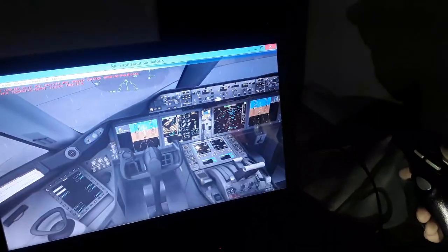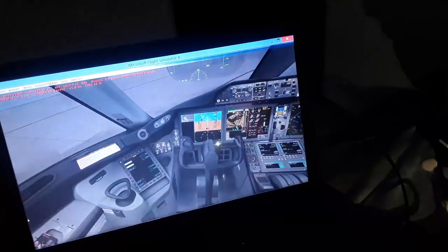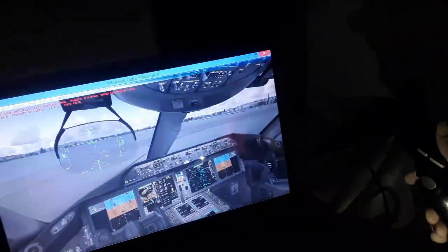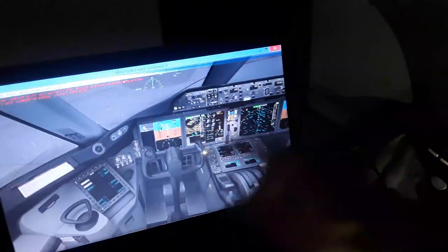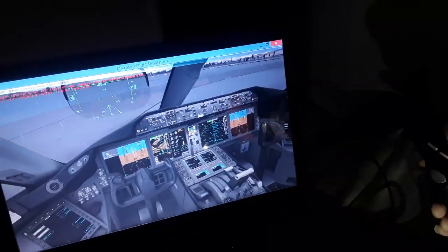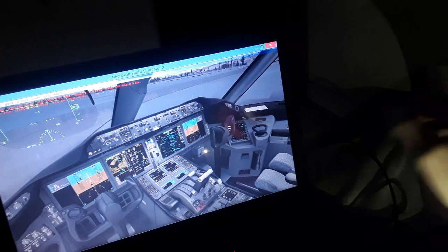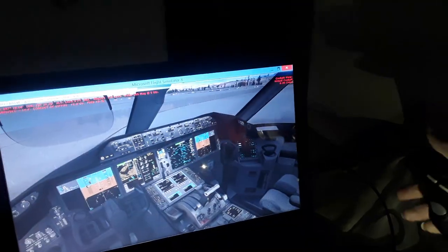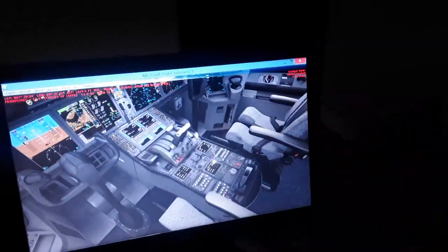The nose wheel of the aircraft is controlled by the tiller and also by some rudder pedal input until we are accelerating for takeoff, around 70 knots. We have some input that is decreasing linearly from 76 degrees to 7 and then to 0. And we have the rudder aerodynamically effective at around 45 knots, usually in most airline aircraft. So pretty much the same for all of them.